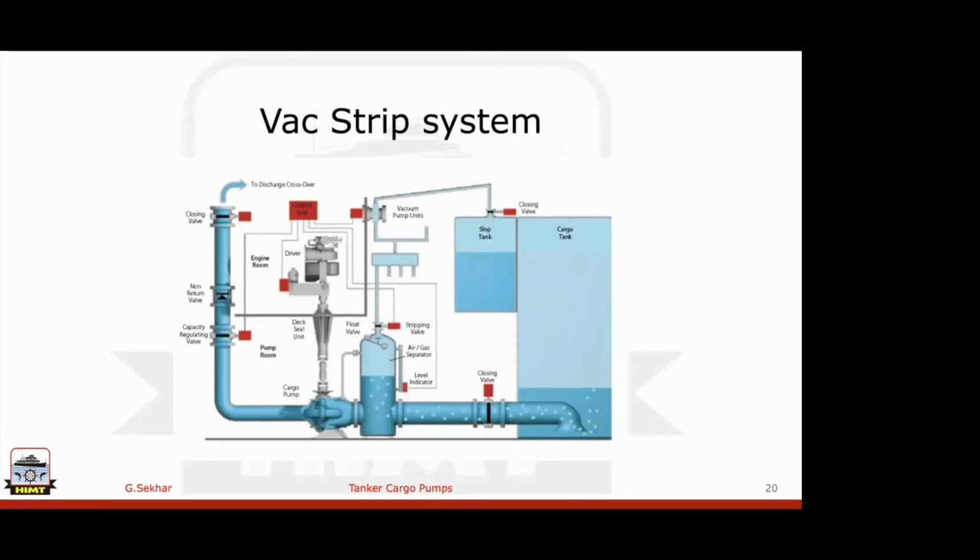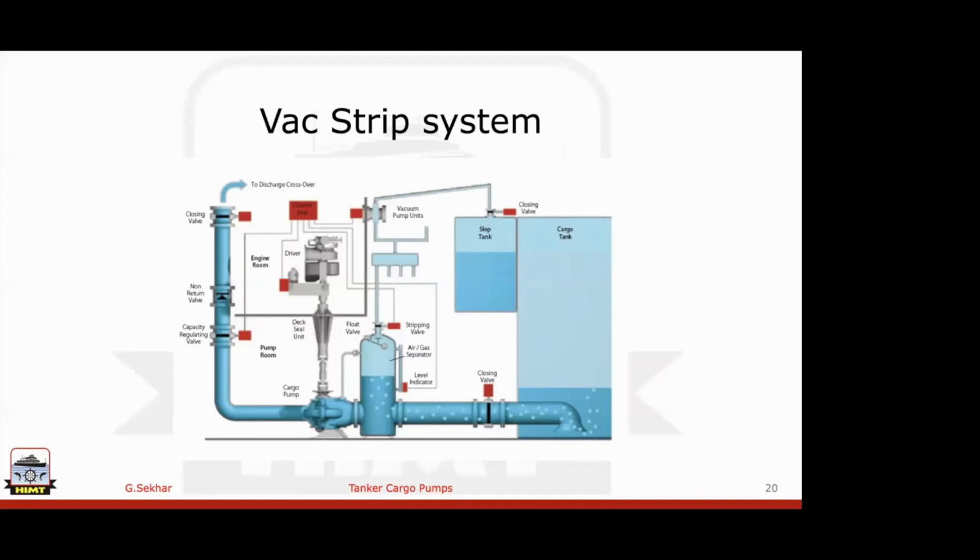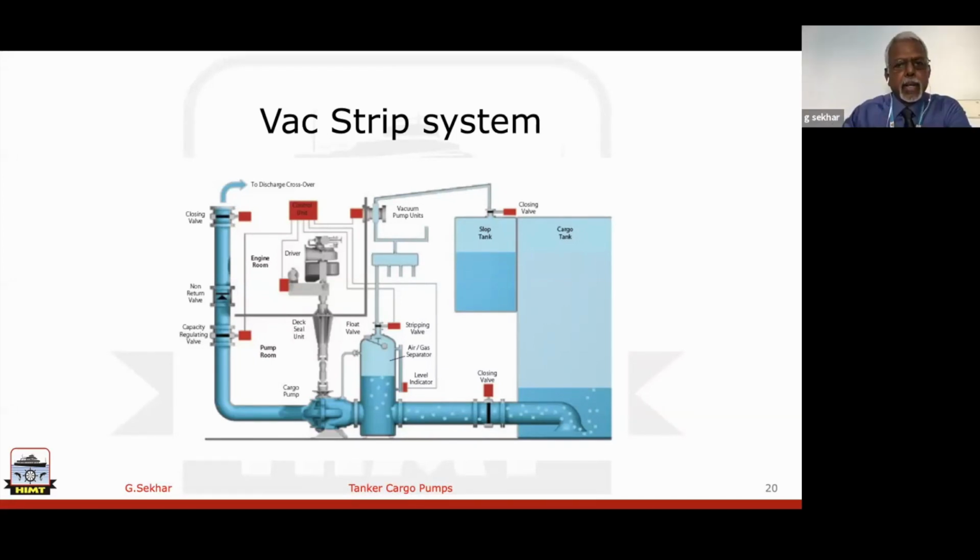Sir, when we are at a critical time, if we close our discharge valve, we will reduce our flow rate. At the same time, we will reduce our friction loss, no, sir? Yes, that also can be done, but the recommended procedure is to reduce the RPM.